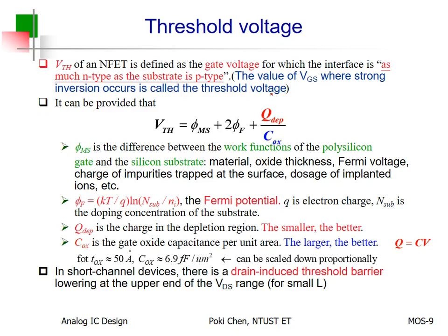Threshold voltage is very important for MOSFET, for you, and even for me, because again, what is the saturation current? There is a term, VGS minus VTH squared, right? So it means to increase the total current, we hope the threshold voltage can be as small as possible, to conduct more current.